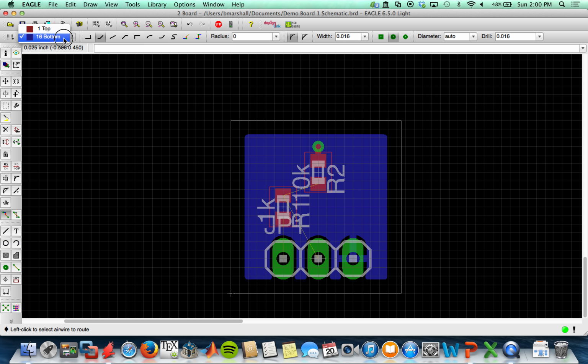So I'm going to go ahead and connect the other guys that I need to up here with the route trace tool. It's a nice 45-degree angle there. And then I need to connect this. So again, it's not the best layout in the world, but I'm showing you. Now notice all this text is kind of... so all the electrical stuff's good. My rat's nest is clear.